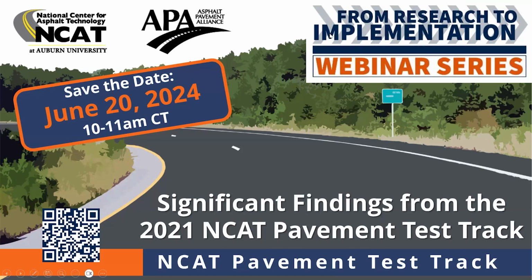No, I think on a low volume road, you see the same crack pattern. There are 2 sections on the track where we saw what you would think would be bottom-up fatigue cracking from a relatively thin pavement, because it showed up in the transverse orientation, and both times it was because of something that happened in the middle of the pavement structure.